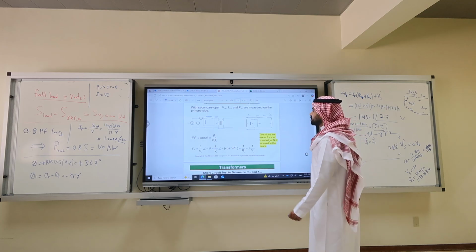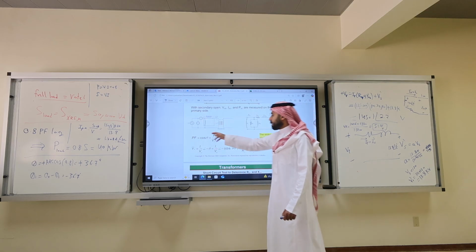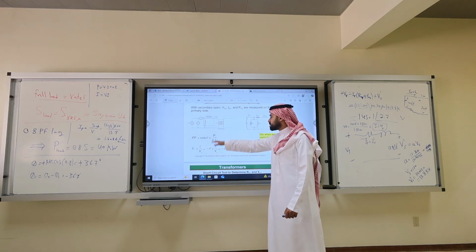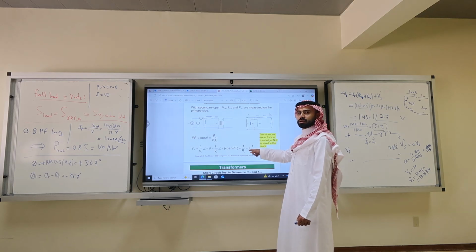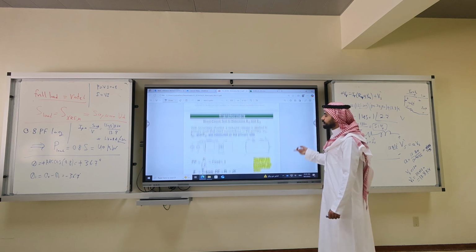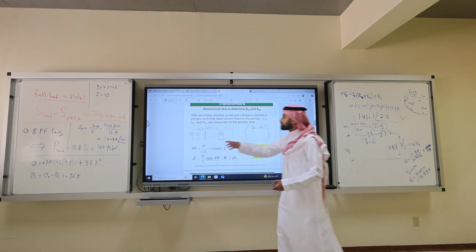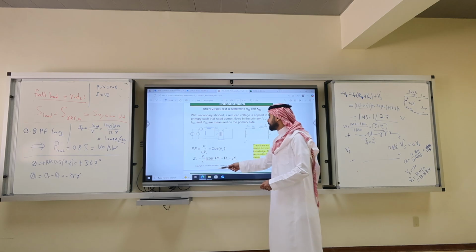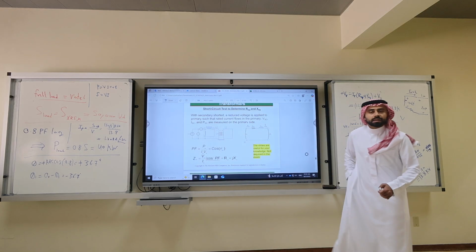You apply voltage, you measure voltage and current on the primary side. Then you get the power factor using the tool. You get the admittance, which is I over V, and then you get 1 over R minus j 1 over X. Then the reciprocal of every number is your components. How about the short circuit test? You apply voltage and current, you short circuit the output, then you get the power factor, you get the impedance, which is R equivalent plus jX, if they're using circuit 3.